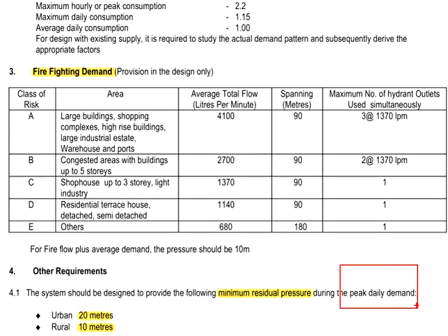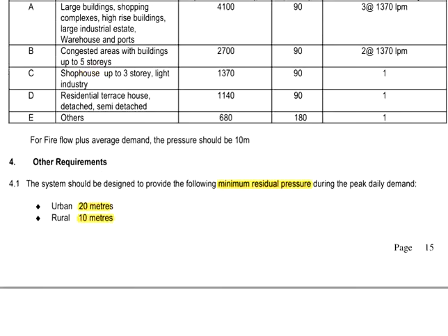During the peak daily demand, more people are using water. This shall be the time that the water pressure may be inadequate. Therefore, we will need to check the minimum pressures in the system to ensure that the water reticulation system is functioning properly during the peak period.